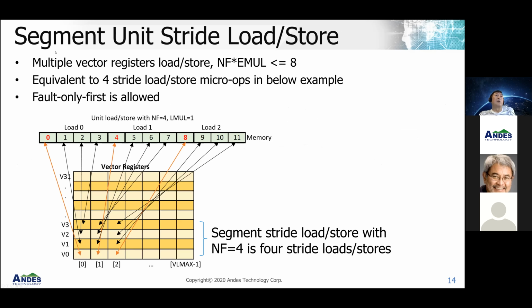Okay, so for the segment unit load store, you load the consecutive data 0, 1, 2, 3 into 4 vector registers, and then go to the next one and load the data 4, 5, 6, and so forth. Note that fault-only-first is also allowed.